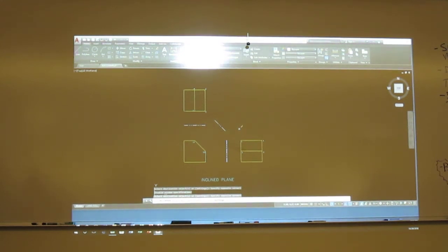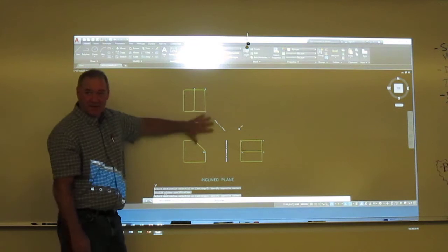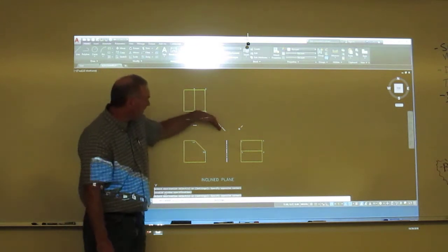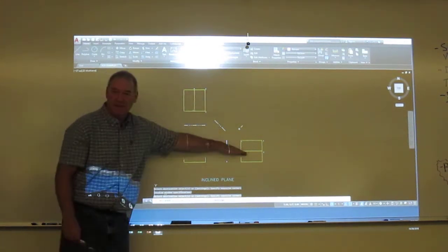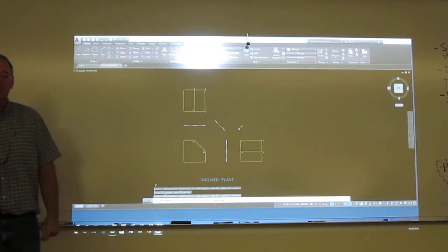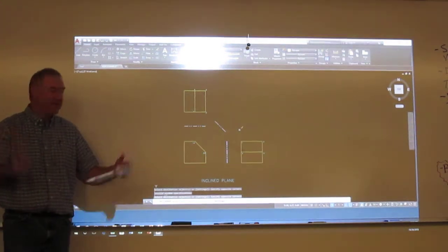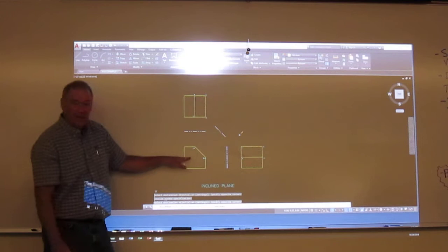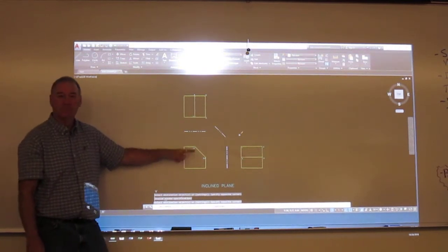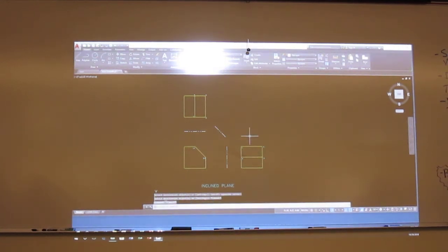Does anybody need a little more time? Okay. This fold line, and this fold line, and this fold line, they're all the same, right? The distance from here out is depth, here depth, here depth. Now, we're going to use the orthographic projection law of 1, which states that I can project perpendicular to any view into any adjacent view. This auxiliary view is adjacent to my front, correct? Yeah, it is. Sits right next to it. It does have the other dimensions in there, even though they're not true.